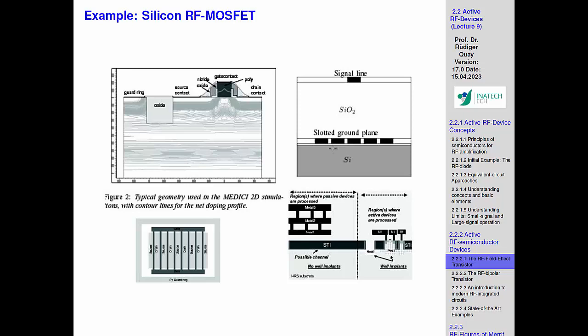And that is a problem, because if you modulate a wave now on the passive side through something which conducts, your wave will degrade quite strongly, which means very high attenuation. So if you compare, that's a problem. And that's why early in the process, people have used a very different concept in silicon. They made these transmission lines on the top, so they're not going into the substrate. They keep the transistors, and next to them, they make other regions where they just make transmission lines on top of the wafer, but at the stack.